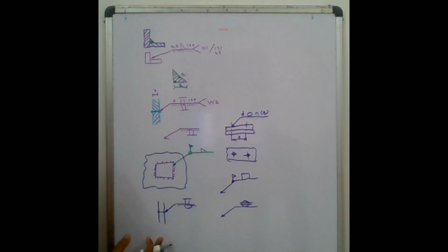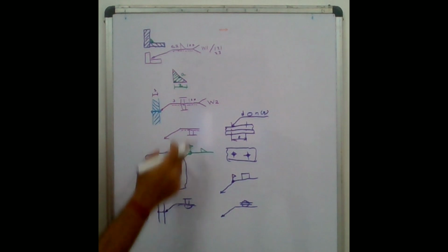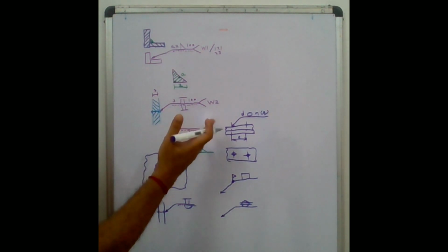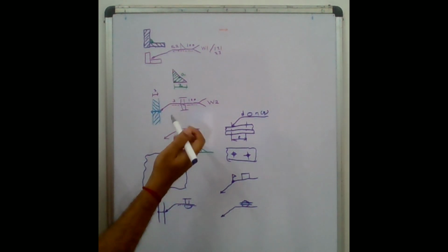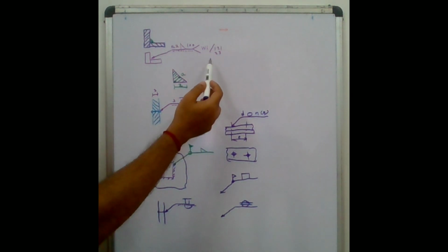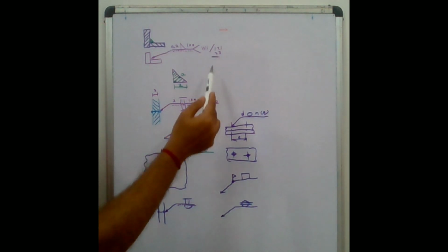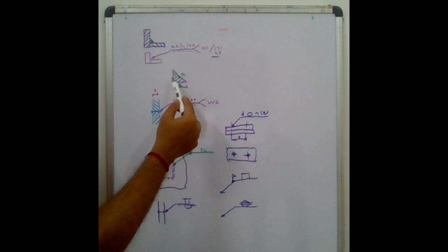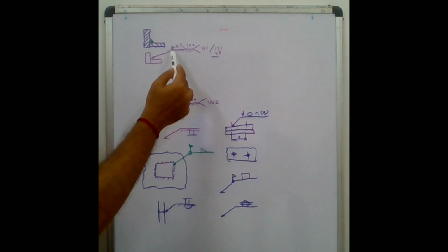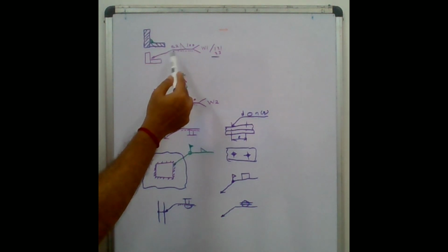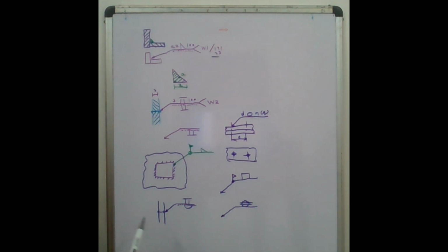So these are the general symbols for representing welding. We can represent this in any welding drawing, and then we can mention the sequence of weld like W1, W2 or any other method, and also mention weld numbers and welding process numbers defined according to ISO standard, and also the weld size, which size of weld is to be done, how long it is to be done, and also the direction. So this is the general knowledge about welding and welding symbols.